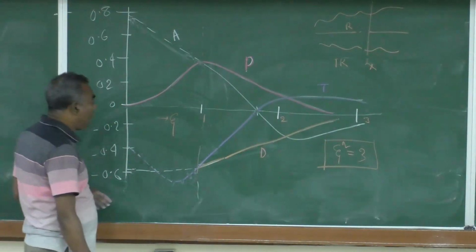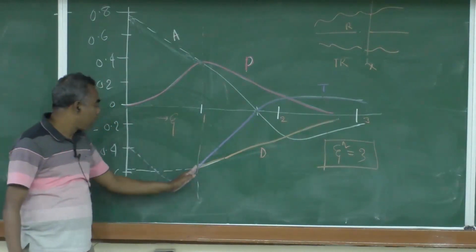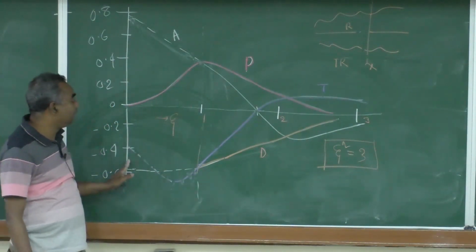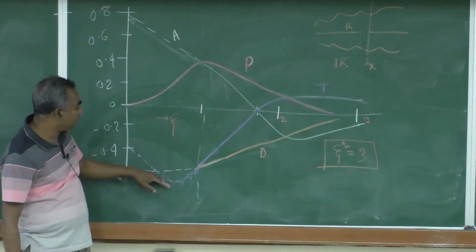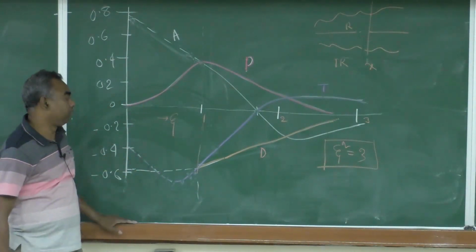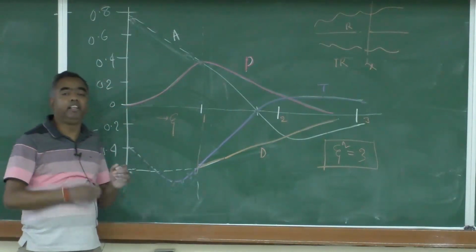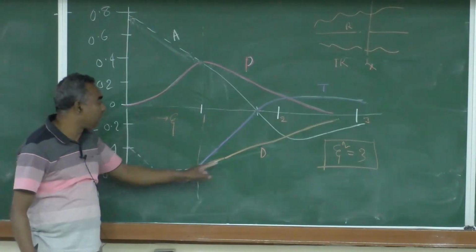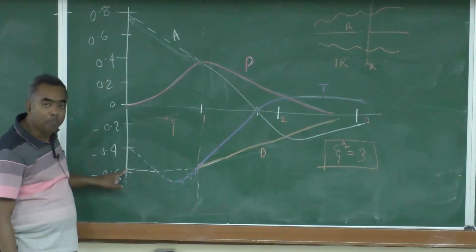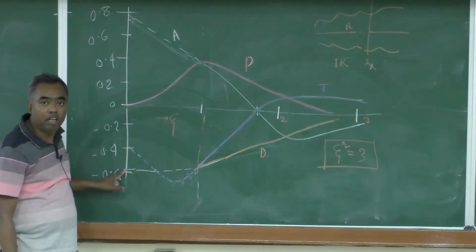Now, the point is, what is going to happen inboard of this j equal to 1? We do not know for advection, transport and dissipation. For dissipation we can say that since near the central line turbulence is highly mixed, we can expect that dissipation will be higher as we approach the central line of the wake.